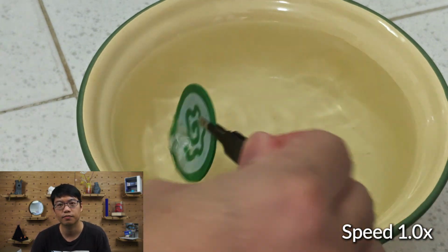Isn't that amazing? Now picture this. As you print, you're actually stretching the material very much like stretching a rubber band. And as it cools, the plastic actually freezes in place and keeps that built-up tension over time. After repeating this process during printing, you can release all that tension simply by putting it in hot water, and that's what we demonstrated earlier. You can then see it spring into a curved shape.